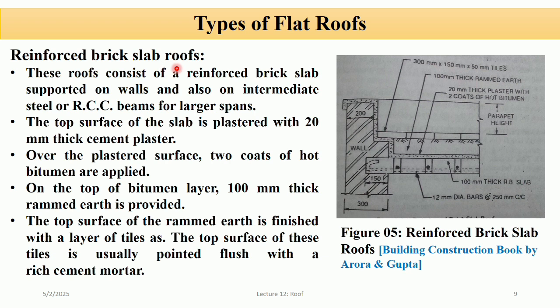Reinforced brick slab roofs. A reinforced brick slab roof is a type of plate roof made using bricks and steel reinforcement, combining the strength of reinforced concrete with the thermal insulation properties of brick and earth. It is commonly used in warm climates due to good thermal performance.